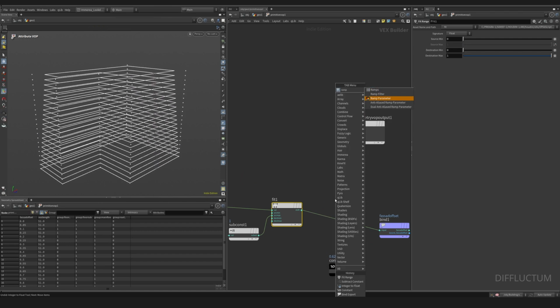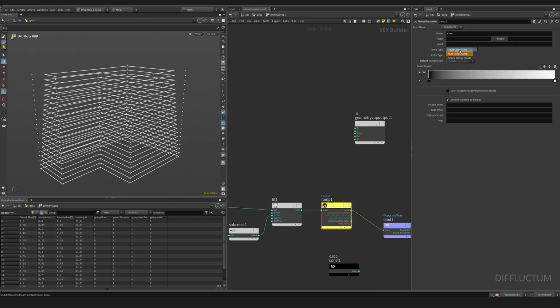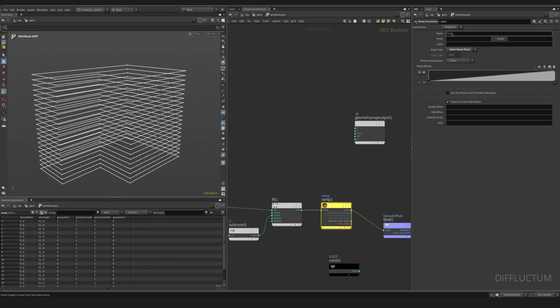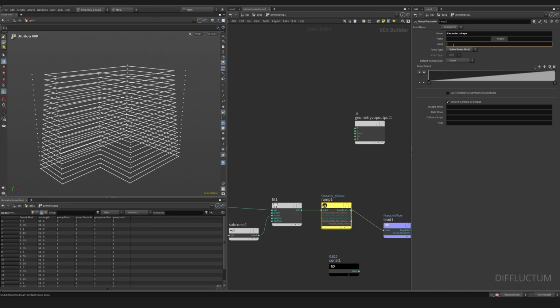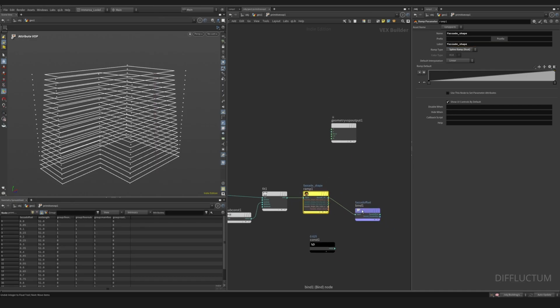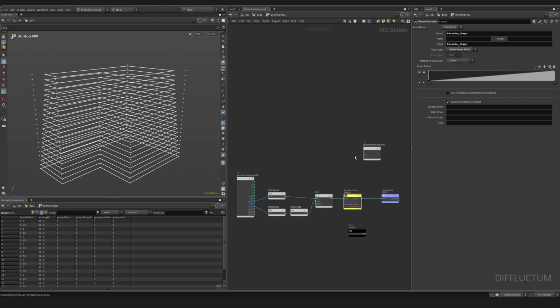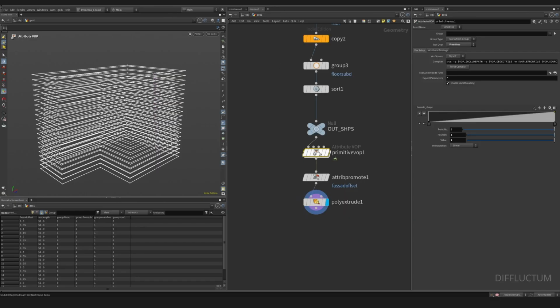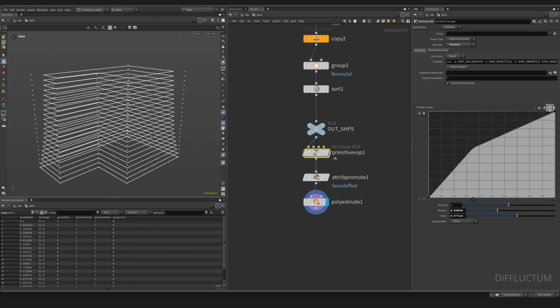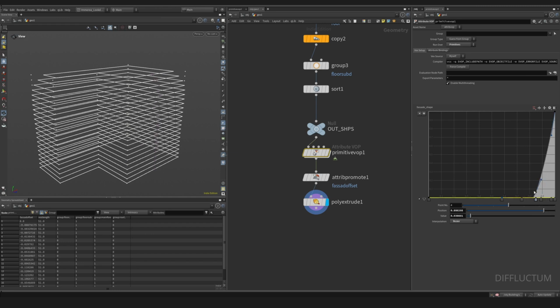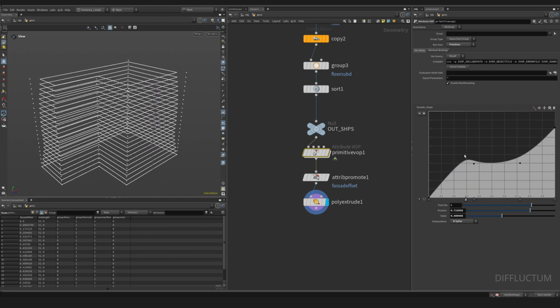After this we add a ramp node and set the type to spline, also give it a name and a label. Afterwards the ramp gets exposed onto the VOP node itself, meaning that changes here inside on the ramp will have no effect. You have to jump back out and use the ramp here on the VOP node itself. Here you can find further interpolation settings, like Bezier curve interpolation, giving you extra control. I prefer to have them as B-splines, and you can play around until you find something you like.